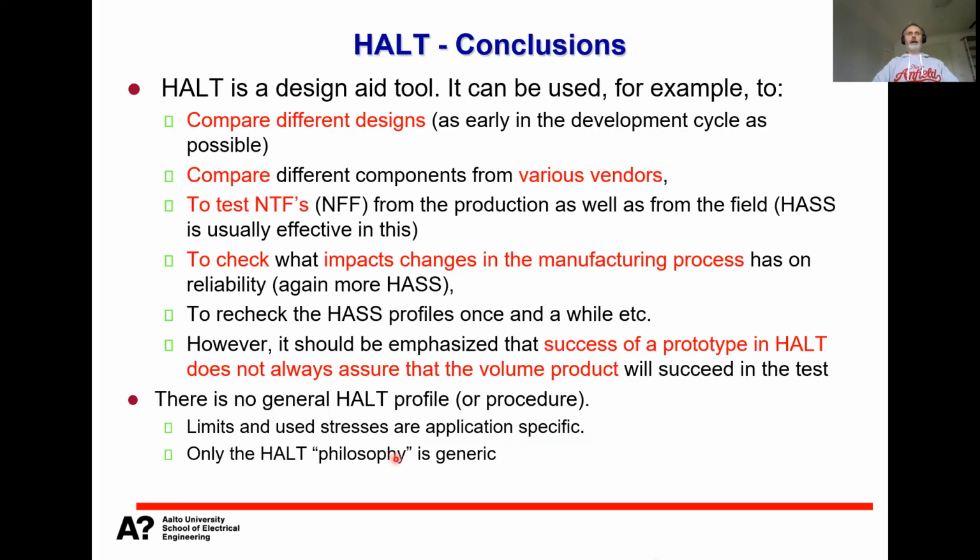So what HALT is good for, and I'm stopping in a minute, is as a design tool. It can be used, for example, to compare different designs. Should I put this component here or there? Should I use this connector or that connector? Should I use the component from this vendor or the material from that vendor, and compare it? You can clearly see which is better than the other, but you don't see how relevant this is.